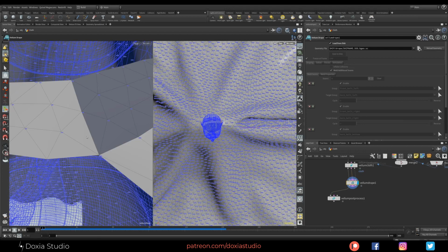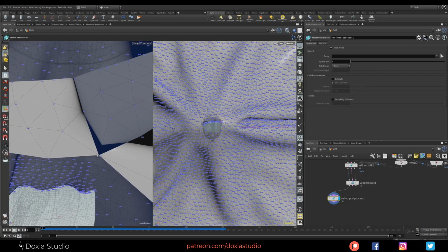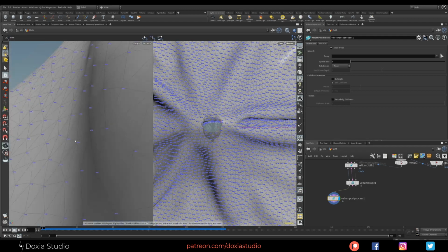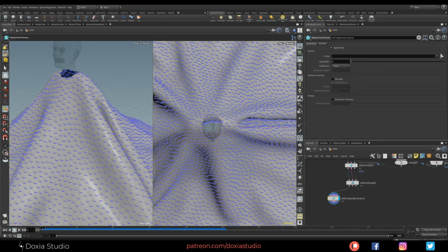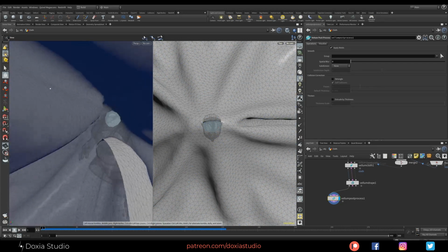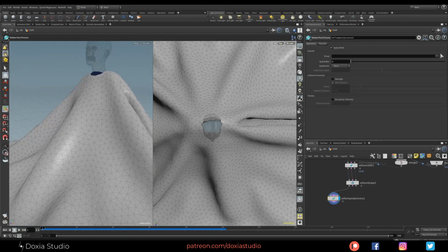And why is that? Because we have the front belt with a point here, the back belt piece has a point here too, and the skirt has a point here too. By applying the Vellum process, you can see that these points are only one now. We kind of glue everything together and we don't have multiple points on the same position because we are welding every single piece, like merging and deleting duplicate points.